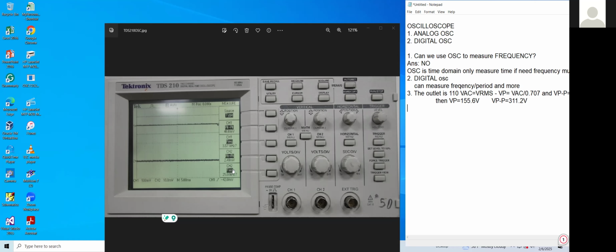But the first thing you need to do is set the windows from the top to channel 1, next one channel 1, and next one channel 2 and channel 2. That's the first thing you have to set. Second thing, on channel 1, what you want to measure. You set it to measure peak to peak.